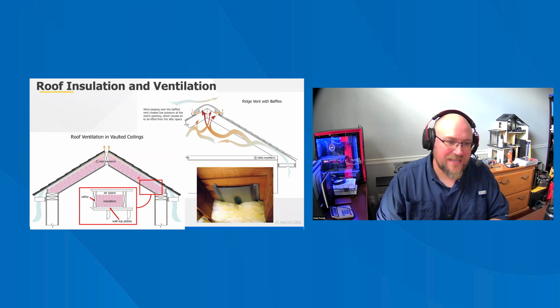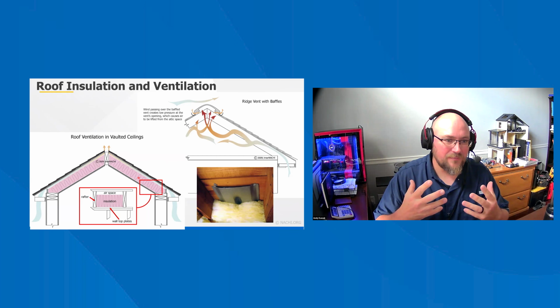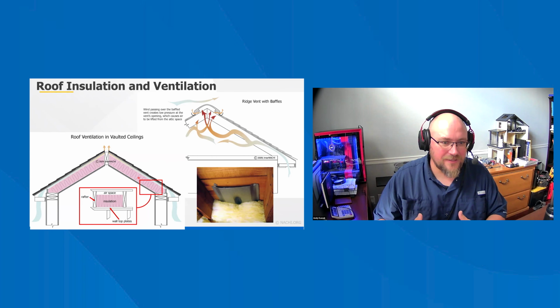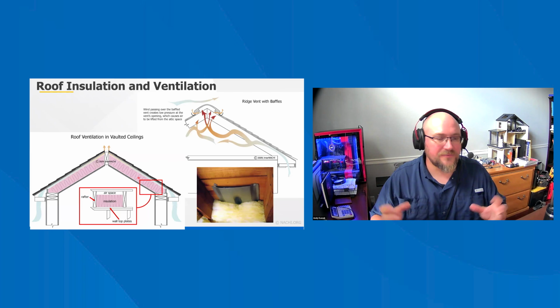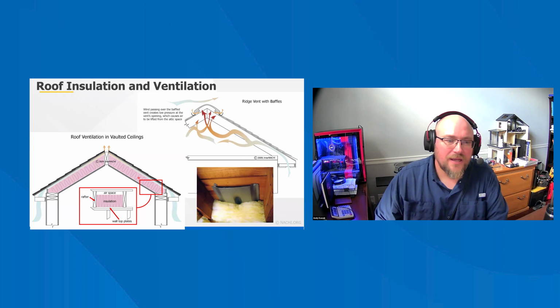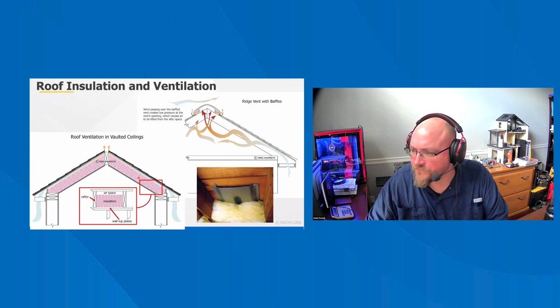So that was a really good indicator that we do not have the right air movement in there to move that moisture-laden air out of that space, which technically was unconditioned. So just keep an eye on that stuff.